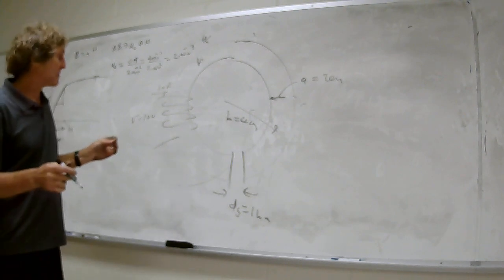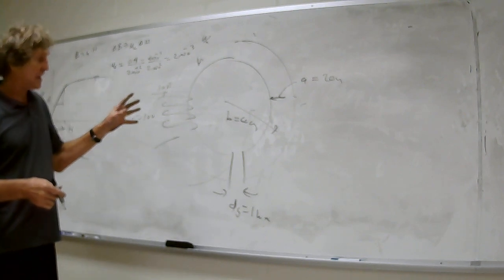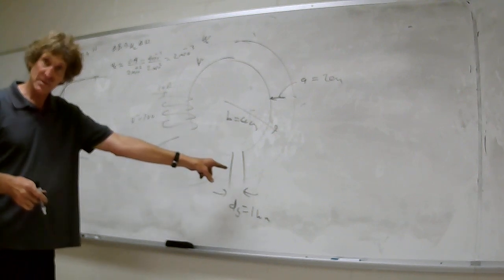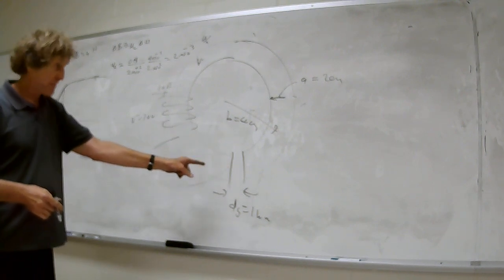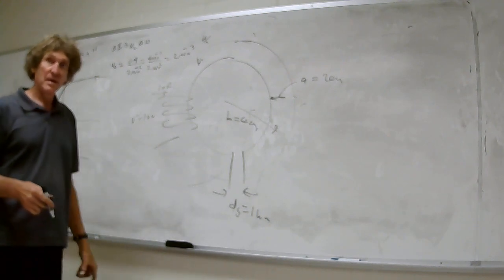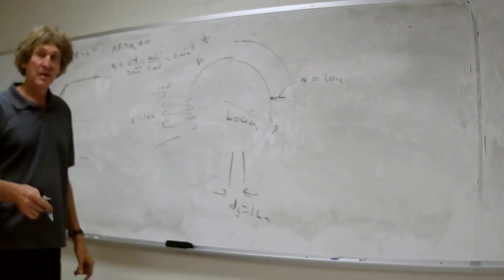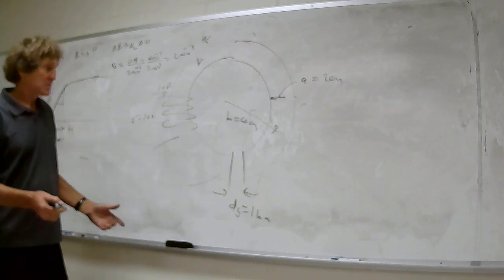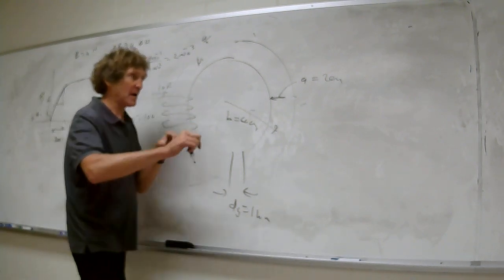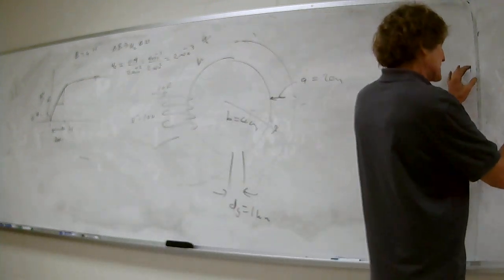All right, now this is iterative. First, you all agree if I cut that bar, I can turn it into 2 series reluctances. One reluctance has to do with that little gap, and the other has to do with this. Are you with me? So series reluctances. You all with me on this, class? Just look. I'm going to cut this, straighten it out. Now what do I have? I have this kind of deal.